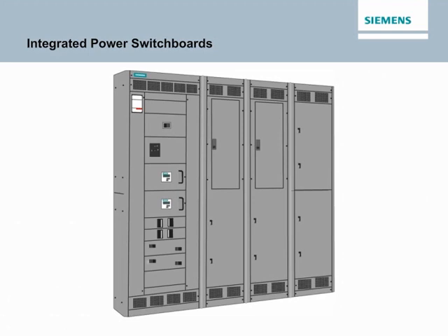IPS sections have a standard height of 90 inches. Optional 70-inch high sections are available. The minimum depth of IPS sections is 13 3/4 inches. Optional depths of 20, 28, and 38 inches are available, and these optional depths may be required depending upon the components installed.